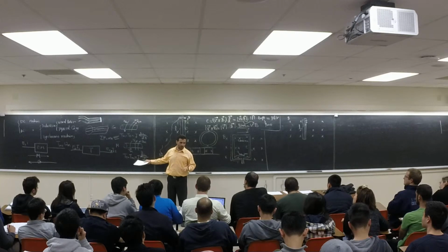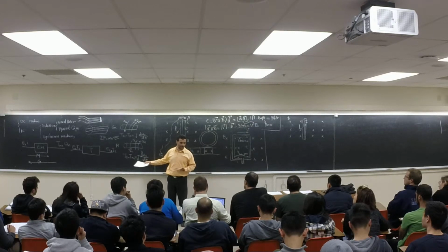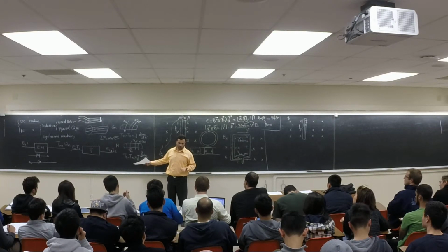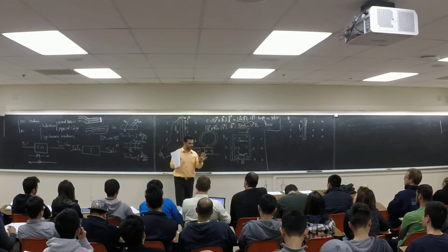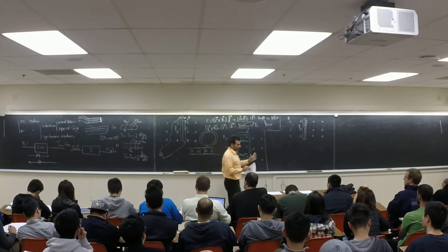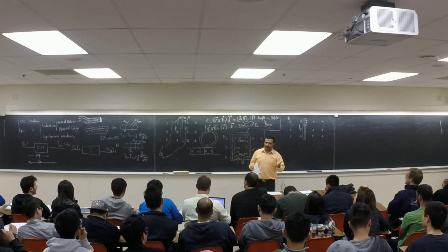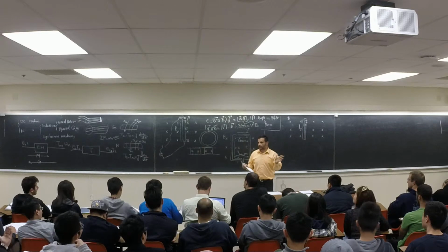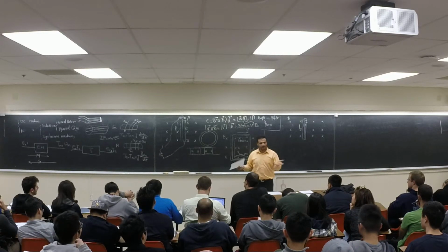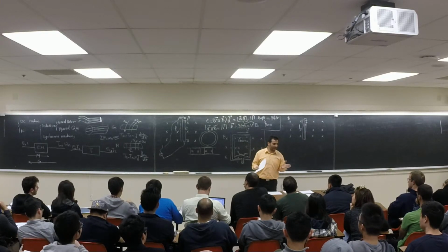If you find out force or torque is in the same direction as the speed, it's a motor, right? Yes. It was as simple as this. You just need to use the left or right hand rule, find out the direction of force, and look at it. If it's in the same direction as the rotation, it's a motor. If it's the opposite of that, it's a generator, right? That was as simple as this.